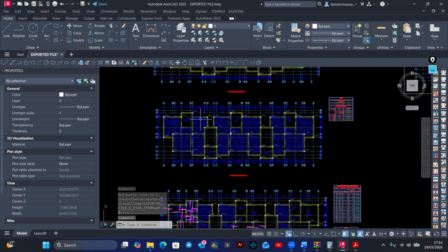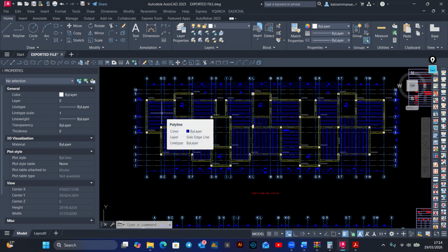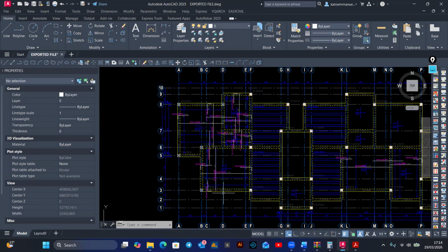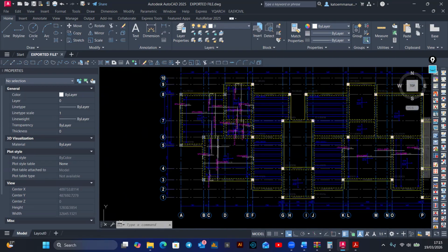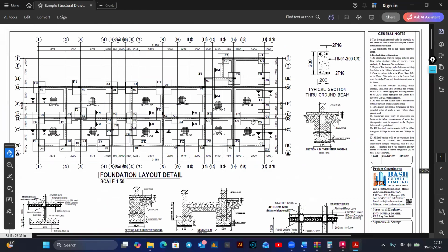You have to get your slab layouts. These slab layouts that will be exported from ProtaStructure will not have clear reinforcement details. For example, here we designed this terrace level, but you can see how the reinforcements have been added there. It is hard to interpret. So it will require you to go into some manual detailing to represent those reinforcements very well, just like you can see in this layout.